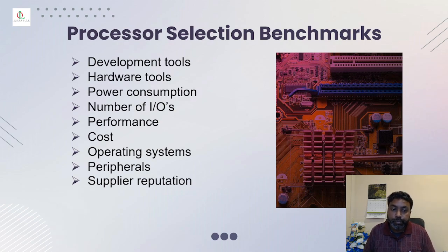And the operating systems, whether your system needs a real big operating system like a real-time operating system, RTOS, or can it run on a simple program, and the number of peripherals you need to use. For instance, if your microcontroller sometimes doesn't come with a CAN peripheral, then you need to get the CAN peripheral as a separate chip, and integrate that into the main system, and that adds more complexity and a lot of toing and froing.